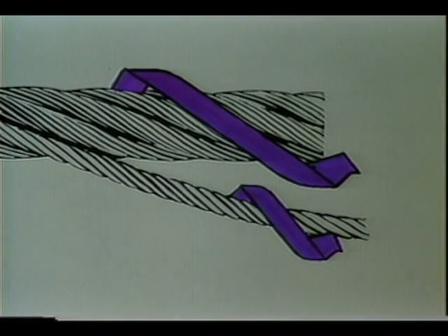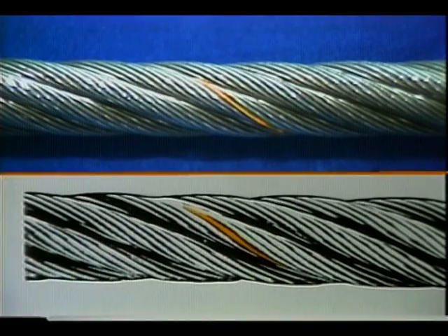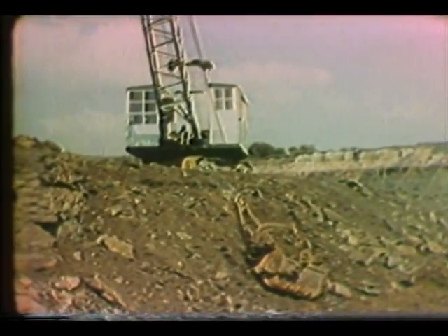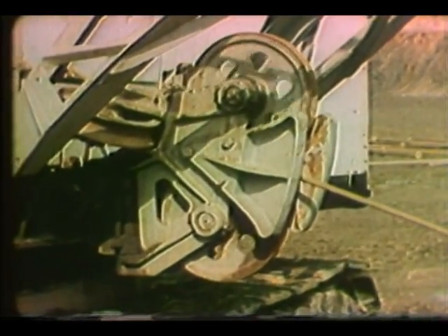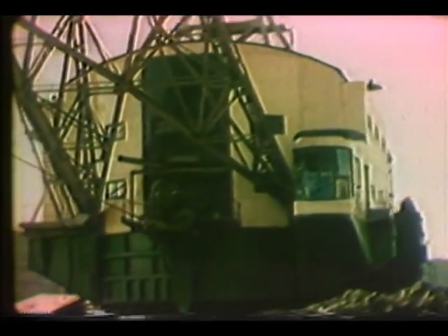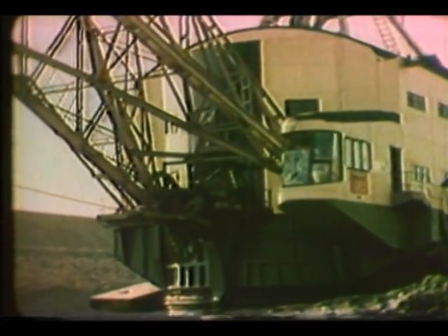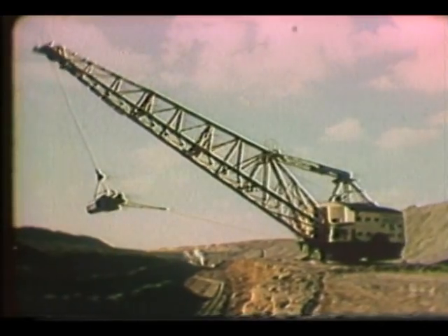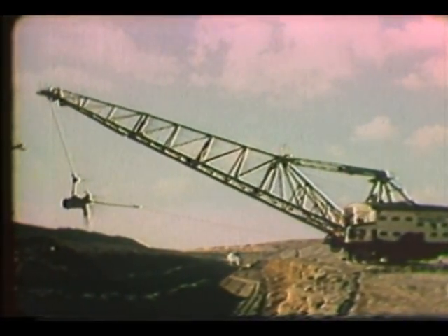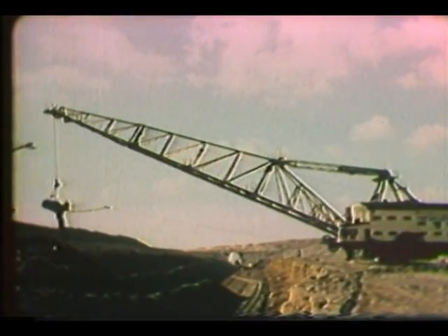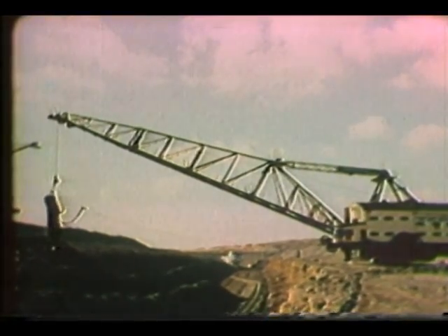In Langley ropes, the wires in the strands and the strands in the rope are laid in the same direction. The outer wires have a greater exposed area than regular lay rope and are therefore more resistant to abrasion. They are also more flexible and have greater resistance to fatigue. However, Langley ropes are more susceptible to distortion, crushing, kinking, and untwisting than are regular lay ropes. For this reason, both ends should be fixed so that rotation is prevented. They should not be used on single-part hoist lines or with swivel end connectors.